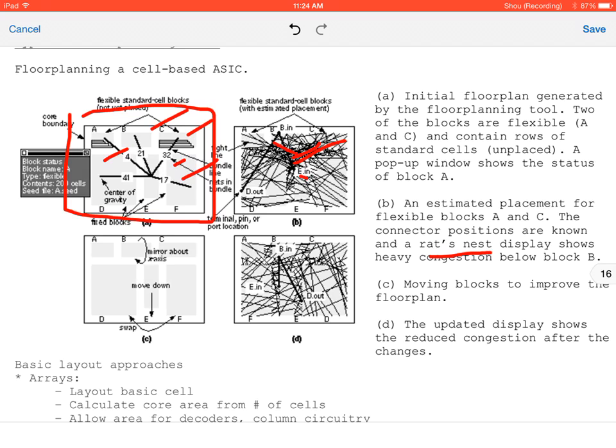It's going to try to wire everything together based on what we need, and it's going to see that and say, how optimal is this? Right? We just discussed all the floor planning steps and we determine optimization, and one of those optimizations is interconnects. So if I delete these red marks that I just put here, you should be able to see the difference in the amount of wires between the initial plan and the final plan.